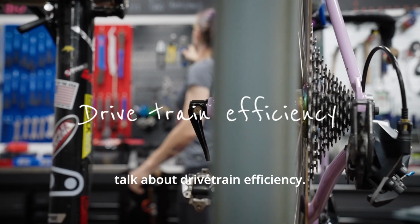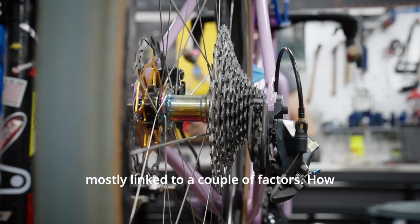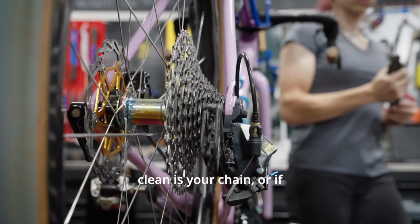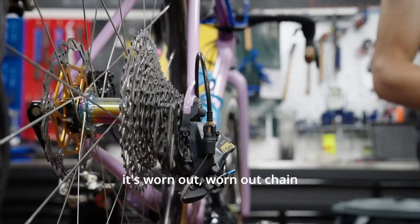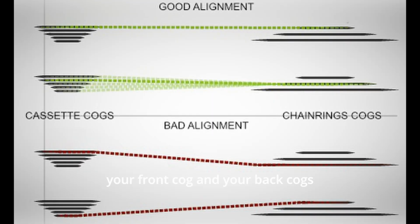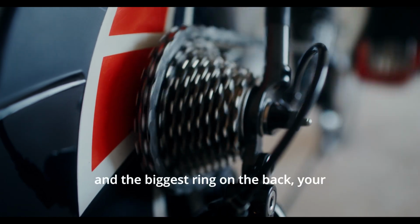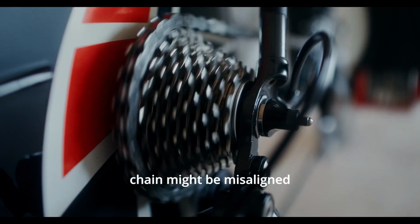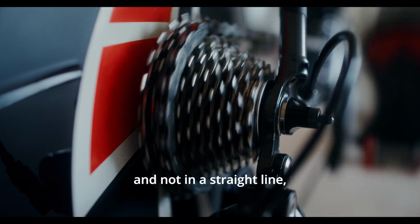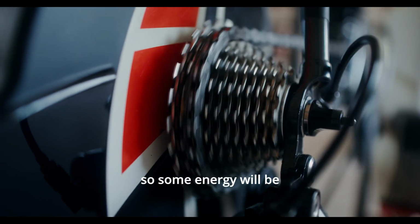First, we'll talk about drivetrain efficiency, and drivetrain efficiency is mostly linked to a couple of factors. How clean is your chain, or if it's a worn out chain, it might not transfer the same amount of power. How well aligned is your front cog and your back cogs on your cassette. So if you do cross chain and you're maybe staying on the big ring on the front and the biggest ring on the back, your chain might be misaligned and not in a straight line, and this will also impair power transfer, so some energy will be lost there.